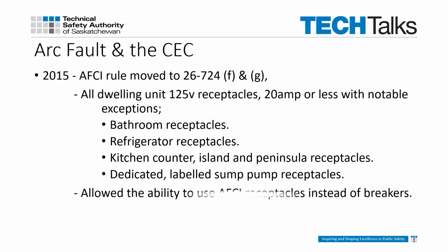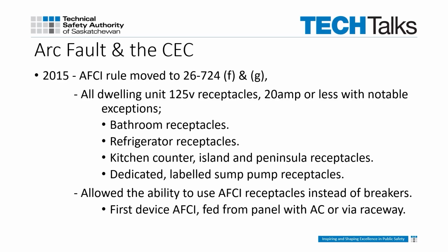2015 also allowed AFCI receptacles to be installed instead of breakers, provided that the first device was the AFCI receptacle and that it was fed from the panel by armored cable or from conductors in metallic raceway or non-metallic conduit or tubing.